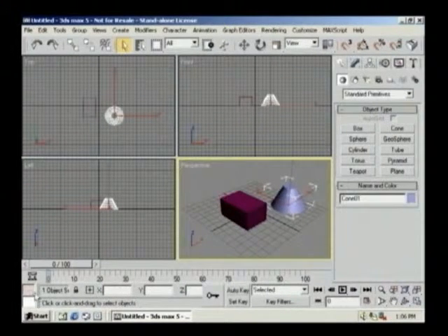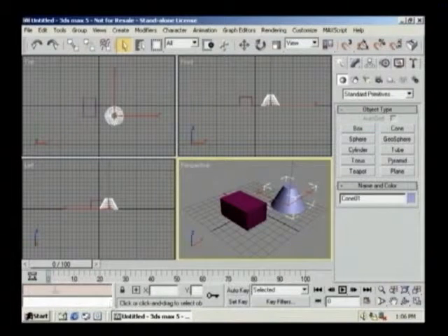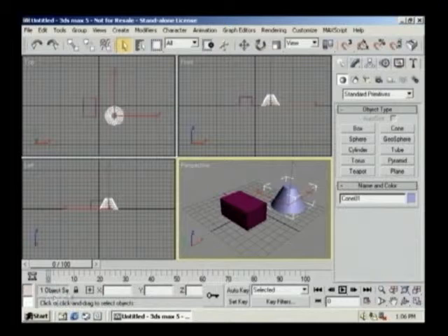In the very lower left corner, you'll find the MAXScript area for creating custom commands in the program's built-in scripting language. Again, I want to remind you that my screen resolution is set to 800 by 600. So these areas are very crowded down here right now, but at a higher resolution, you would be able to see all these different sections very clearly. Right now, it's just a little cramped down here. Like the status bar and the prompt line, which gives us information about our scene and the commands or actions. I can hardly even see them down here right now. Next to that, you have the lock selection button. To the right of that, you'll find the type-in transformation box on the status bar for entering precision transformations.